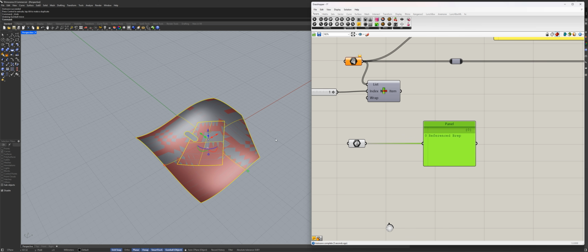What's inside this referenced BREP is two surfaces. They're not merged, they're still two different surfaces, but they will be treated as one geometrical, not parametrical, object with base geometrical properties. If I explode it on its components, it will get back to our original surfaces. This command in Rhino and Grasshopper has the same name, explode. If I do that, I type explode, plug that in, and plug that into the panel. You're going to see that indeed now we have two different surfaces.